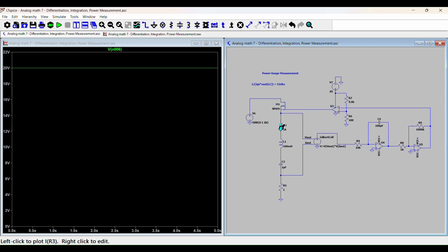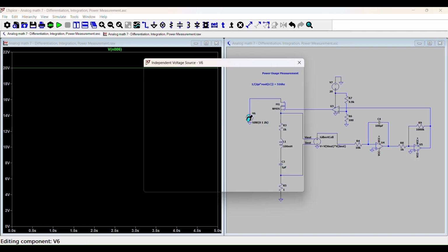So there's not going to be that much power dissipation across the resistor, because the resistor is the only component that actually burns the power. The inductor and capacitor do not emit power; they store and release power back into the circuit. The time when the power dissipation is the highest is during resonance, where the capacitor and inductor basically cancel each other out and have the highest possible current through the resistor. That's determined by this equation, 1 over 2 pi root LC, which for this circuit is 516 hertz. So at 2K, we see that the power dissipation is really low, so it never hits the threshold.